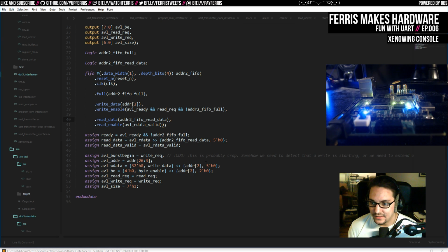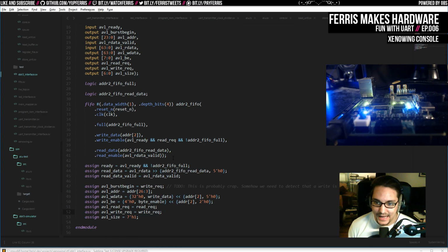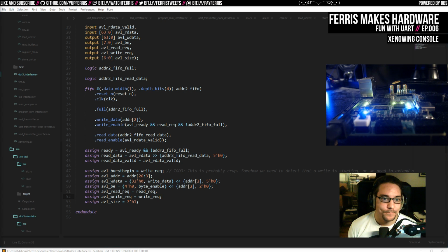So we take bit 2 of the address and stick that in a FIFO. Whenever we get a read, we put that part of the address into the FIFO, and whenever the underlying memory interface gives us a word back, we pull that address bit off the other end of the FIFO, and decide whether we need to shift the data that came back when giving it back to the memory mapper. So it ends up being kind of simple, and I was happy with how simple that became.